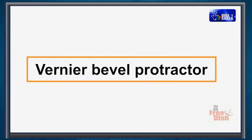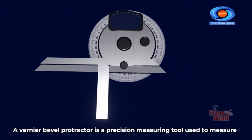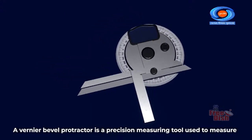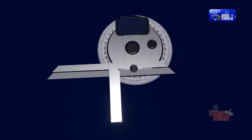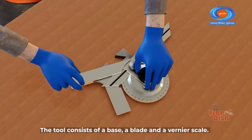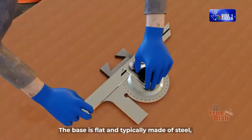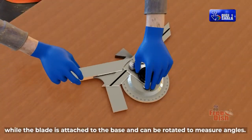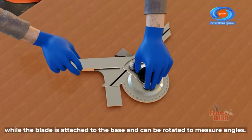Vernier bevel protractor. A vernier bevel protractor is a precision measuring tool used to measure angles with a high degree of accuracy. The tool consists of a base, a blade, and a vernier scale. The base is flat and typically made of steel, while the blade is attached to the base and can be rotated to measure angles.